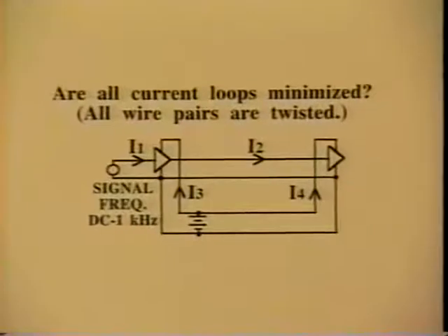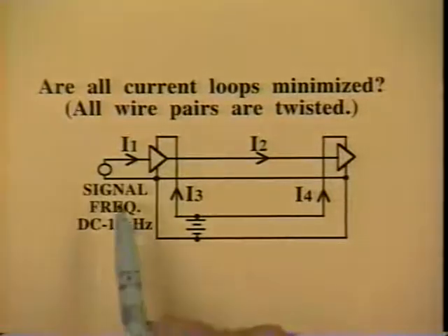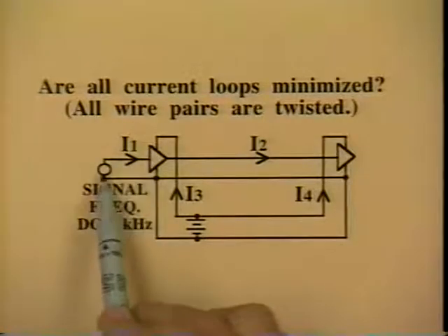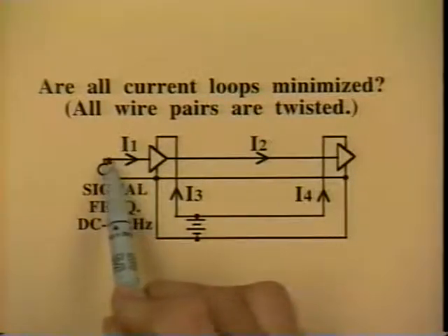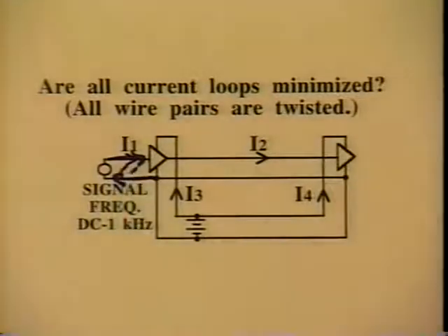In this circuit here, this is really more about routing, but I want to show that, again, we've got to be careful to separate routing from grounding. I want to know, are all of the signal currents under control? The most critical current is probably this one coming from the signal source. That current has a path over and a path back, and no other path.